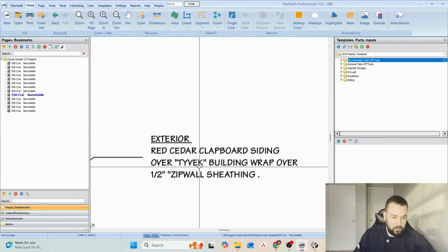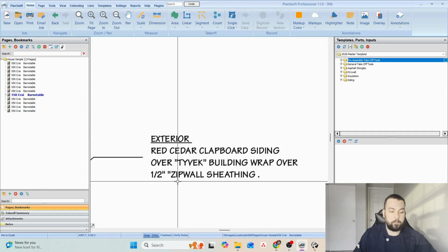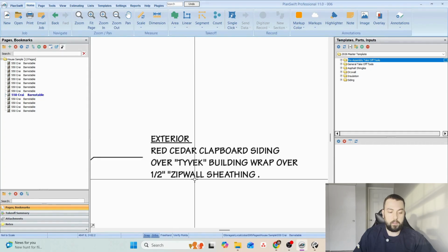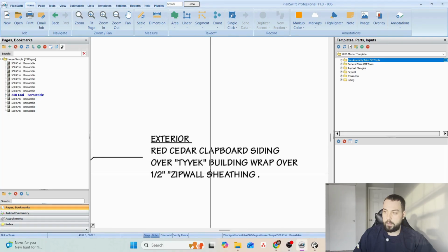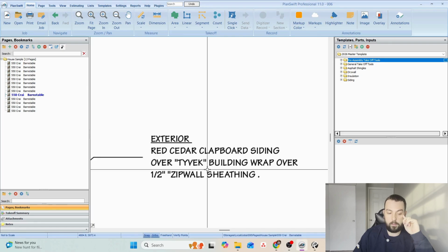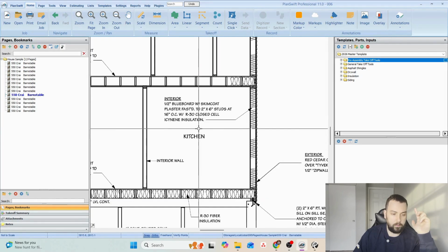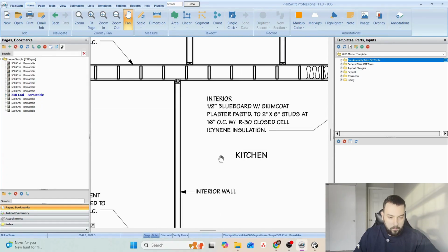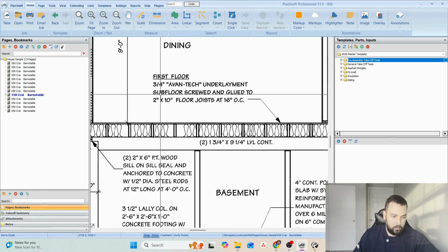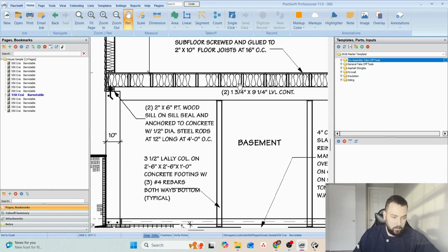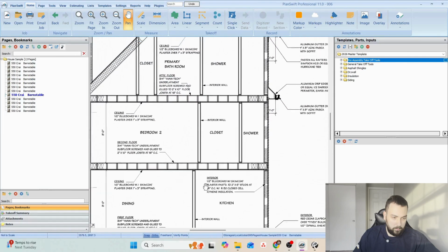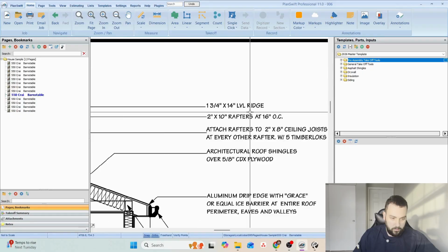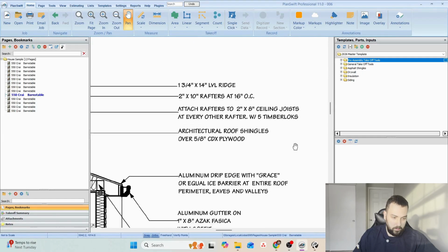I found it odd, because ZIP wall is the structural sheeting outside, but it's also asking for a tieback. So this house is gonna ask for 2 AVBs. That's gonna drive the price up, but let's follow the plans. Okay, there's a spacing here. Strappings, type of plywood, in this case Advantech. Okay, some lally columns in the basement, some rafters, collar ties, plywood.